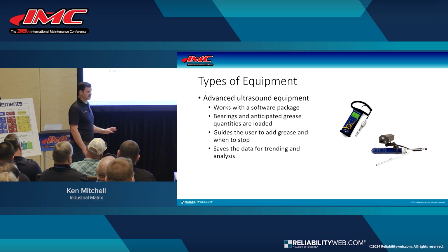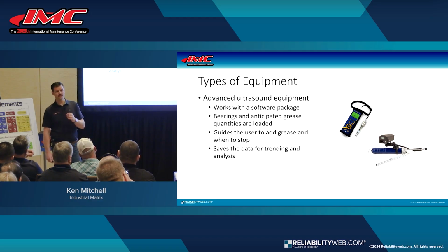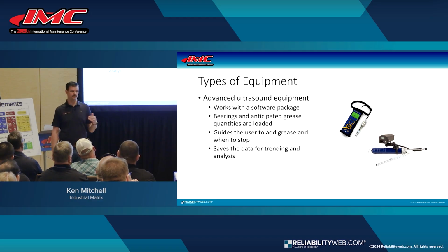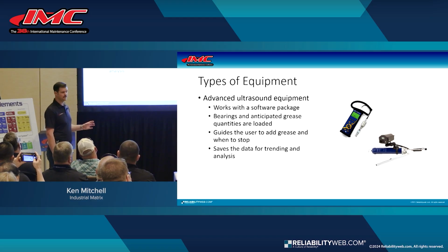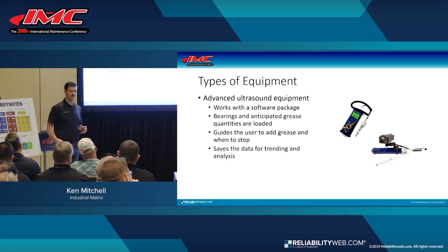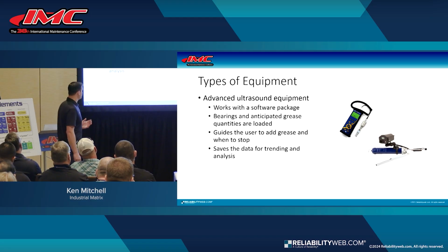This typically works with a software package. So it's going to allow you to pre-program what bearing you're on. You can put in your quantities. More importantly, you can trend that bearing. As you go out, take your ultrasound measurement, and lubricate that bearing, that's going to allow you to take that data, download it, and put it back. Now you're doing some condition monitoring in addition to your lubrication. With that, you can do some analysis as well, reports, all that fun stuff.